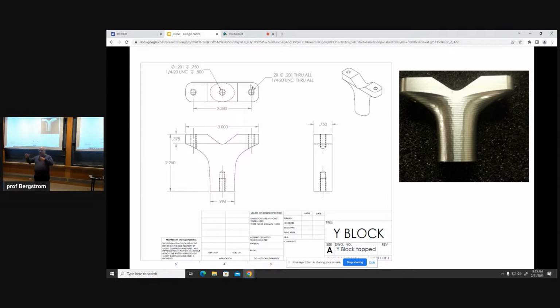So the plane got better because we made the part better, but it also got $100,000 a year more expensive to make the plane. If we had done the correct tolerance on that hole, you could have just added another pin in the stamping process and not moved it to the machine. It wouldn't have cost any more to make. So small tolerancing mistakes can be expensive.